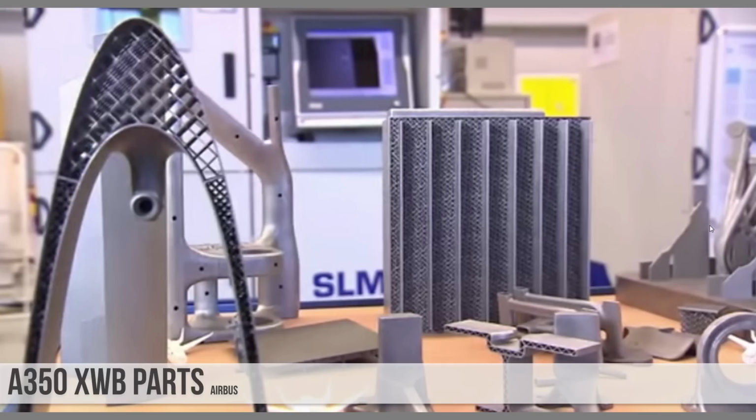Here's some examples from Airbus. These are A350 XWB parts. It's a wide body version of their new flagship aircraft. This is a variety of parts, and I don't know the story behind each one, but I just wanted to make note of the interiors of these parts. They're all lattice structures. All right, so the exterior part might have the same shape as a traditional part, but the interior is lattice structures of varying densities. You see in that part there on the left in the foreground, it has a varying density throughout the part. Towards the bottom right, we see something that almost looks like an I-beam. It's a little bit more complex than an I-beam.